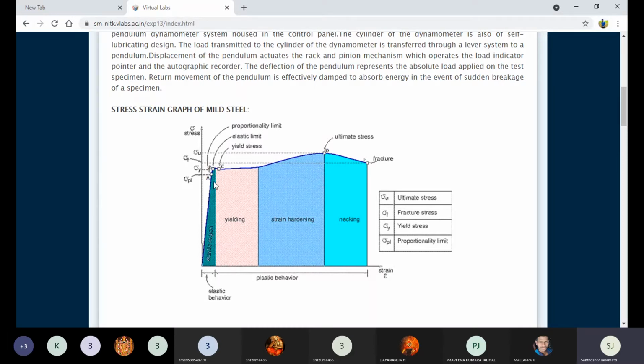But once the load crosses the elastic limit, the material yields. Once the material yields, permanent deformation begins, and there will be a permanent mark that we can see. This is the yield point, which indicates that plastic deformation begins to start. The plastic deformation starts at the yield point and ends at the fracture point. This length we call the plastic deformation, right?